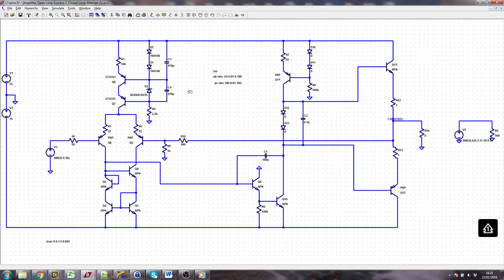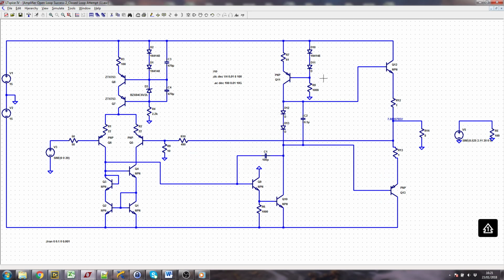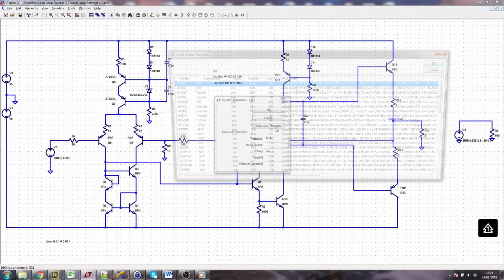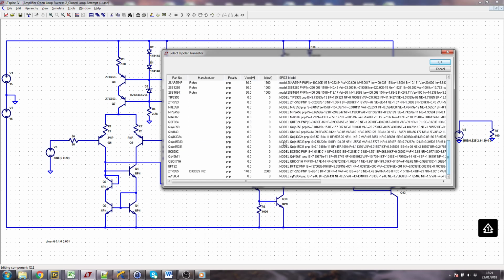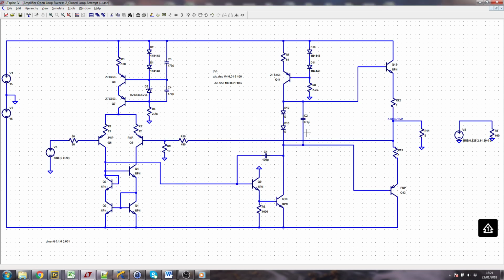So this current source, very similar to this one, only a slightly simpler design. So we'll just make the necessary changes. We just make the models a bit better, so we can expect a reasonable simulation. And I might make this 2K2 as well. Fine. R7's a different value to R3, so let's have slightly larger current. In fact, I should be expecting about 10 milliamps out of here.